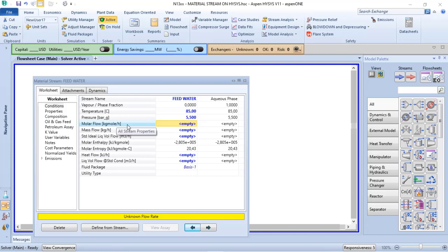Most often you find molar flow as kilomole per hour or mole per hour when you have textbooks sharing examples on how to perform chemical process engineering calculations, or eventually if you work with lab work or chemical reactions, you will use kilogram mole per hour as input to your process simulation. In real life, most often we use the mass flow or its variation as ton,